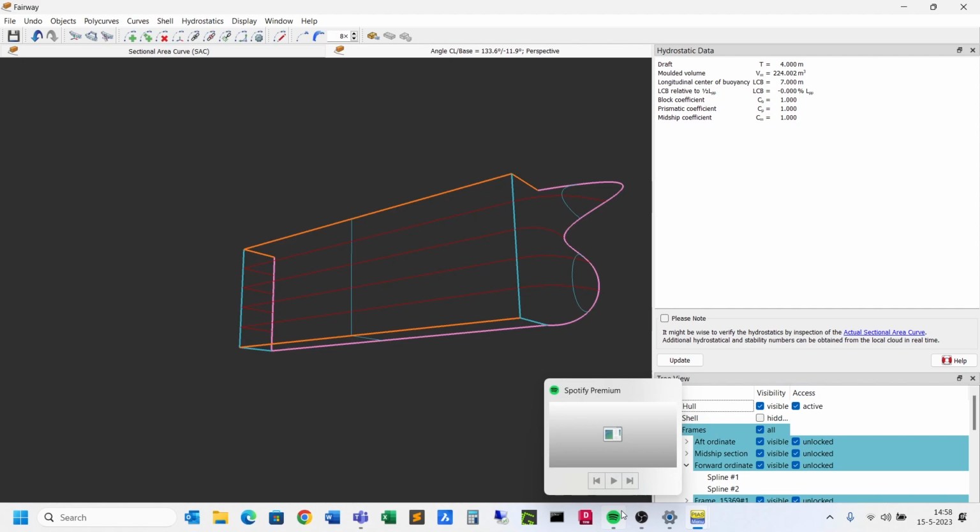Most of the time I use several solids for one model, only when you convert it to bias and you have different compartments in both parts, then you need one solid, but else you can use as many solids as you want. If I do the hull with three different solids, are the three different solids going to give me hydrostatic properties? Yes, you can send them back as separate models.